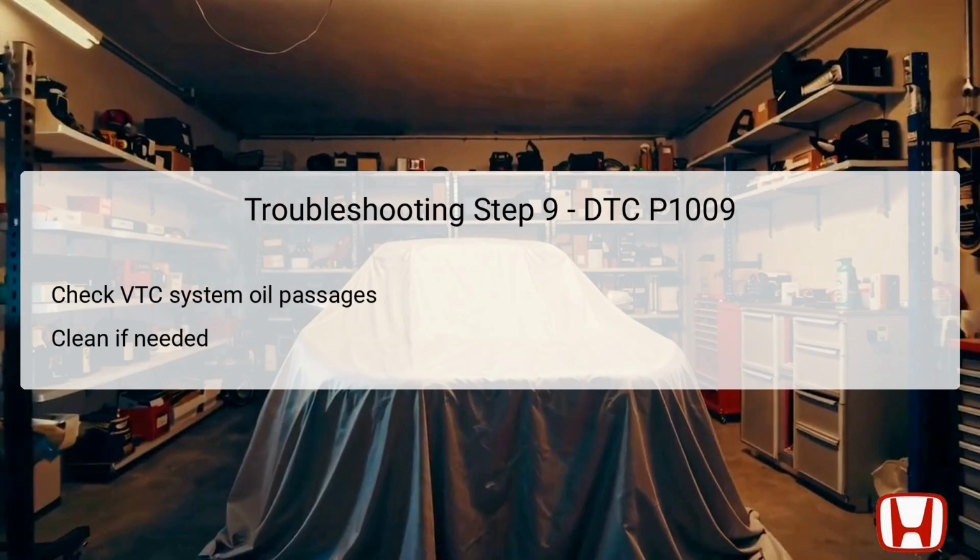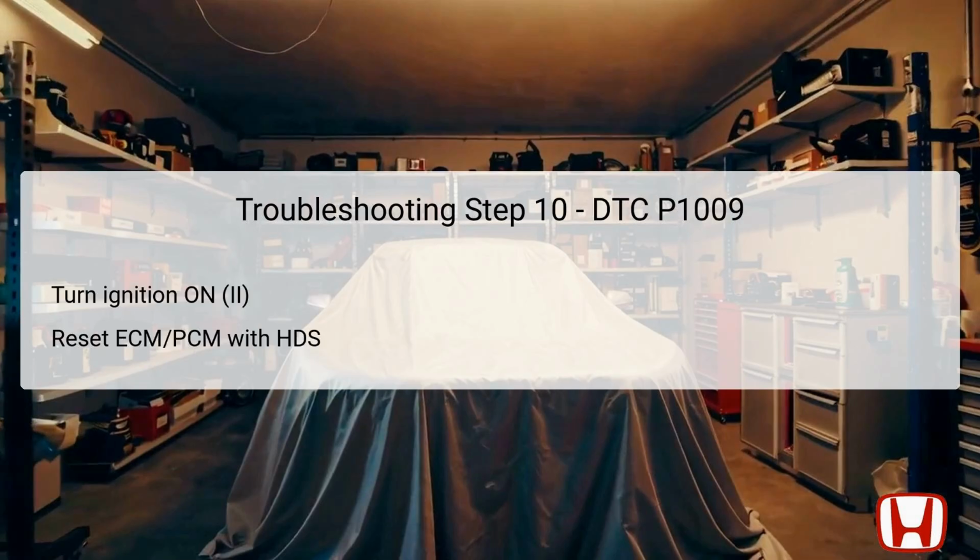Documenting the condition and any cleaning measures taken is important for proper record keeping. After ensuring all components have been checked and serviced, turn the ignition switch back to the on position 2. The next vital action is to reset the engine control module, ECM, or powertrain control module, PCM, using the HDS. Resetting the ECM/PCM clears any stored faults and initializes the engine control system to baseline conditions.